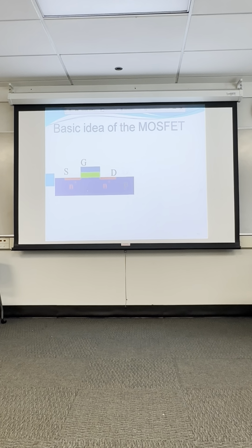So it's basically a given MOSFET, and this is another kind of simple animation here. It shows the P-type body. There's some embedded drain material, embedded source material, and then there's a metal gate structure here. And then the substrate usually is taken to ground. And if we ground the source, remember we had that in one of the images.